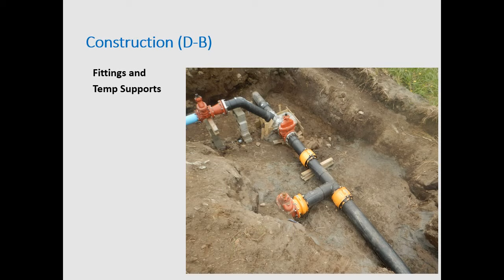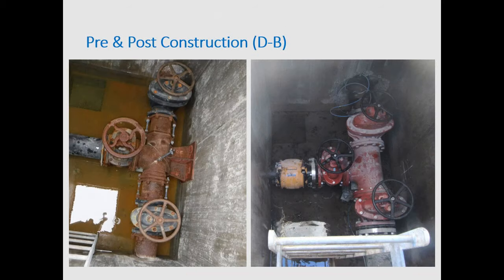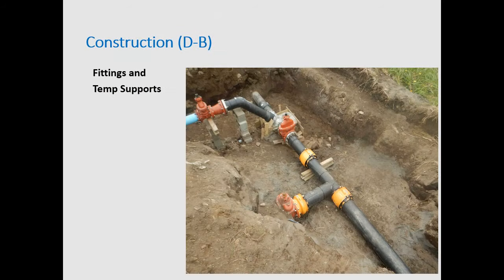In some discussions with the contractor, there were recommendations: you may want to have some other options, something that gives you a little bit of flexibility to do the connection from HDPE to HDPE. So we recommended that they take some Romac Alphas out there. And needless to say, they were very grateful for that recommendation, because it helped them make these connections where things weren't perfectly aligned, and HDPE in tension trying to do an electrofusion just increases a lot of risk. It's not that it's not doable, it's that you've increased a lot of risk.